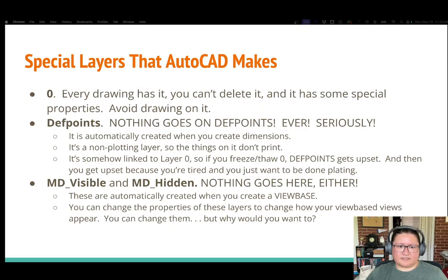The other thing is that if you freeze layer 0, Defpoints gets upset for whatever reason. So just assume, don't do it. Never draw on Defpoints. Don't mess with it. Don't change it. Don't move anything that's on it. Defpoints is dead to you. Don't draw on Defpoints.